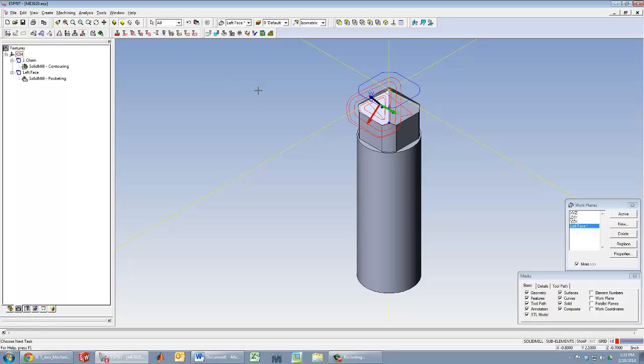Swarf operations require different inputs depending on whether you're using the rolled swarf or the surface swarf, as you might imagine. I'm going to use the rolled swarf just because I found I like it a little more. The primary difference between the two is that the rolled swarf requires what's called a rolled feature. The surface swarf, on the other hand, does not. If you're wondering what a rolled feature is, hang on about 30 seconds.